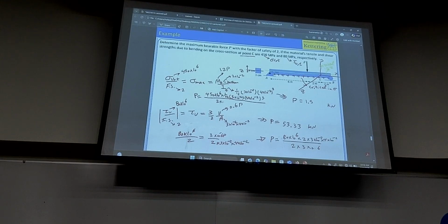So for your left side, you show on your screen, this is on the denominator, which is 2.25. And divide that, the stress multiple is 460. Divide that, because of the units, you have to multiply by 10 to the 6. And then IZ should be equal to 1.6 times 10 to the negative 7. Is that what you got?